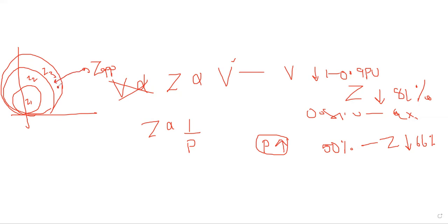If it falls under this zone, what will happen? My zone 2 will pick up. And if the line length is more, obviously it will impact my zone 3. So my relay will operate without any fault, only based on the load encroachment. Generally, due to high power flow or voltage drop, these scenarios take place. To avoid these scenarios, we have some quadratic characteristics,